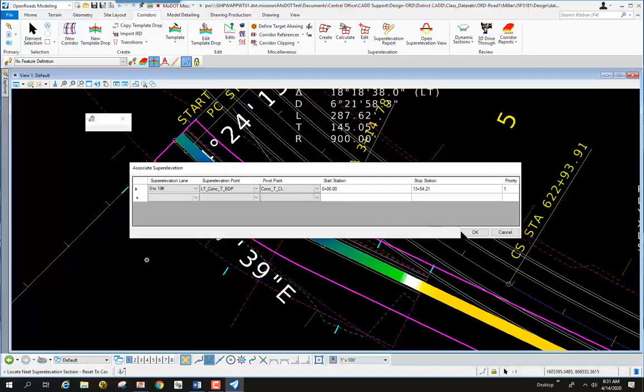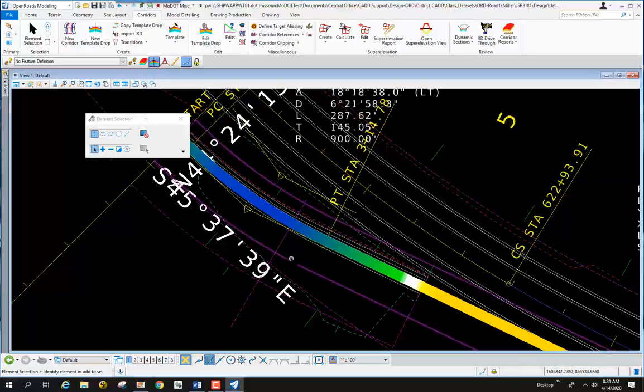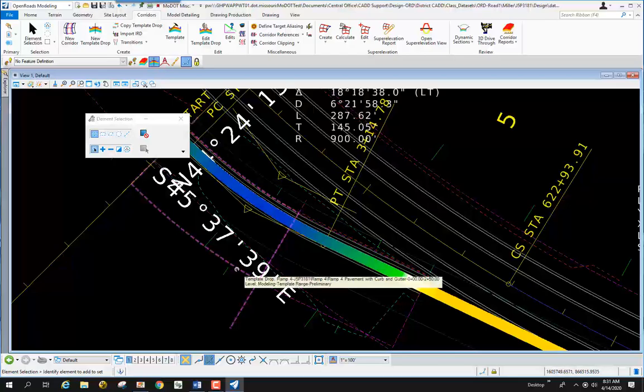And when we hit OK to this, it's going to create a point control that's going to adjust our cross slope of our pavement. So we'll go ahead and select OK to that. And before I show you, well, let's go ahead and show you the superelevation. To do that, and this is on page 636, step 25, we're going to open up the cross-section view.